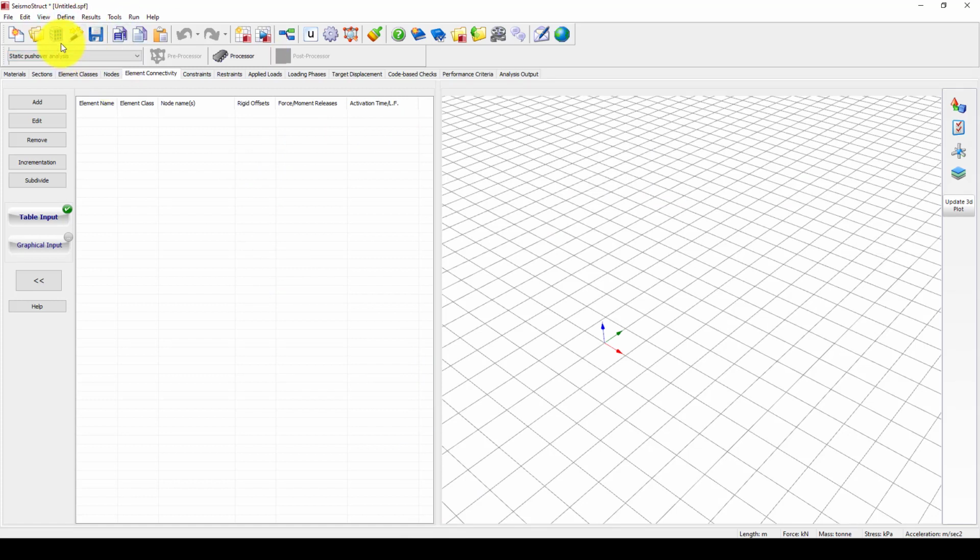In case you select the first floor, second floor, third floor, that's also up to you, but when you're using automatic, the program will determine that the base of the structure should apply the time history. And also you can change the type of frame modeling. So now here the frame columns and beams are called elastic hinge full space frame elements.